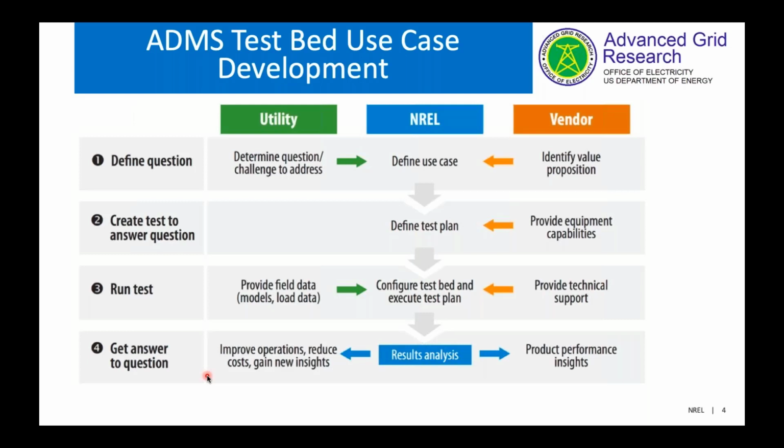That's the way we look at defining the test plan, and also trying to understand how we come up with configuring the test bed. At the same time, we talk with vendors or the ADMS manufacturers to understand how we can communicate with their device so that we can set up a real-time test bed to test different algorithms going forward. Once we configure the test bed, we use the real data from the utility, their models, their load data, and define the test bed based off of the real utility data. And then we analyze the test plan based on the application that we are looking at.